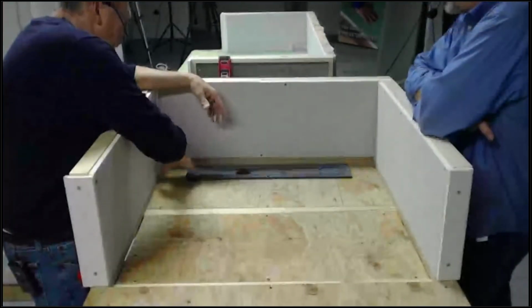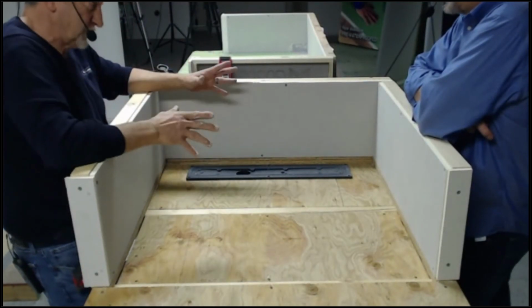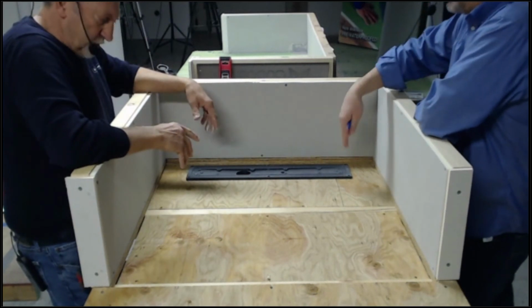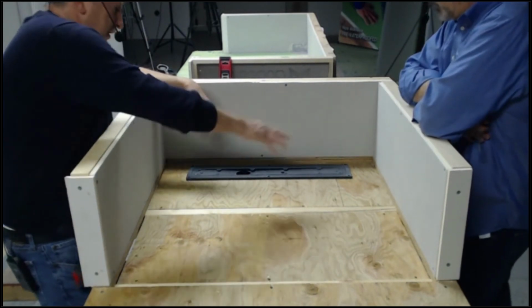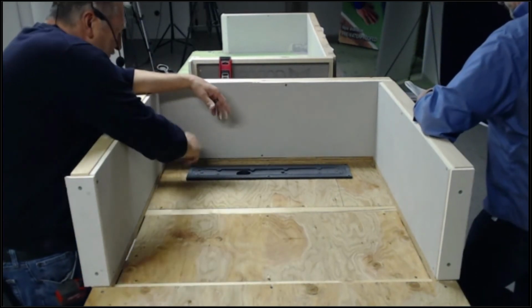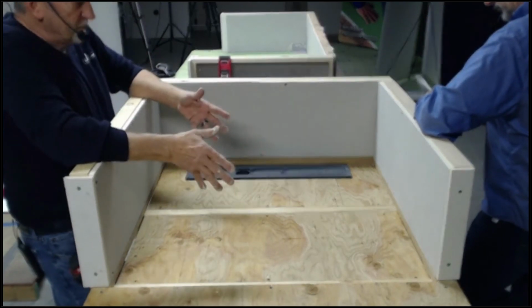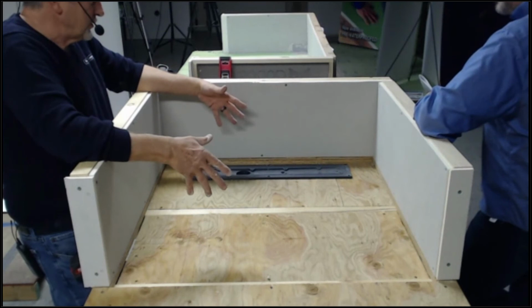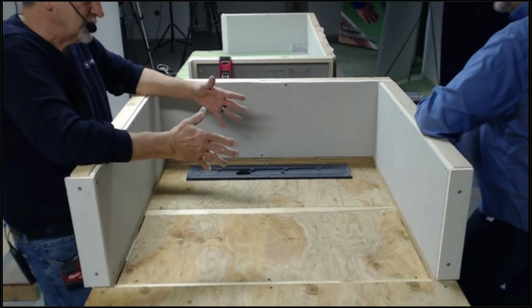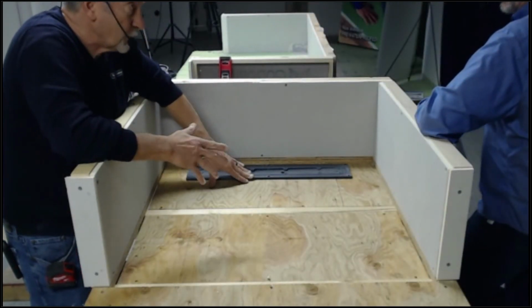Now, if you cut that substrate out, you may have to do some blocking to make sure you're not going to have deflection in your substrate, just like we talked about previously, which is easy enough to do running in this direction. You put that in before you put your substrate in. Then if it's flat and level, you'll just put your screws in there and lock your drain down. In this installation, I have basically 3/8 inch deep. So I'll just use mud, there's mud by companies that you can mix, and it'll go from 0 to 2 if you want.